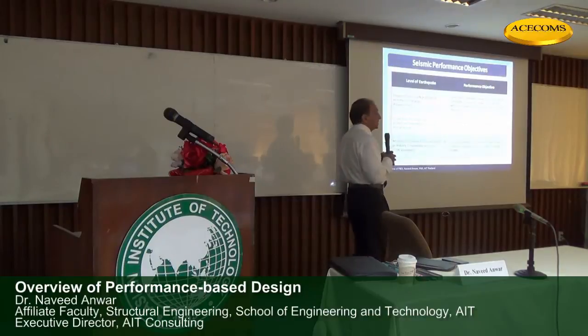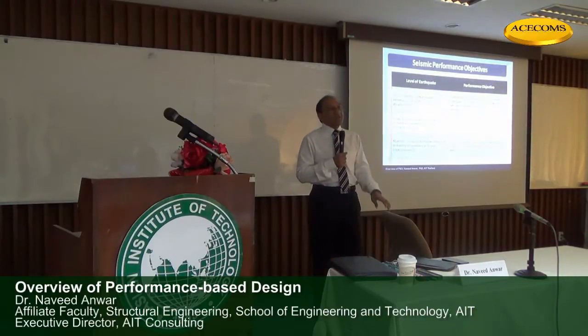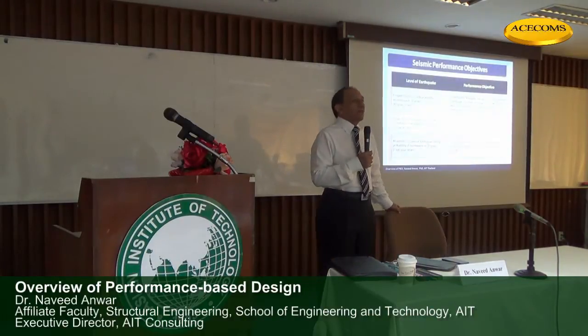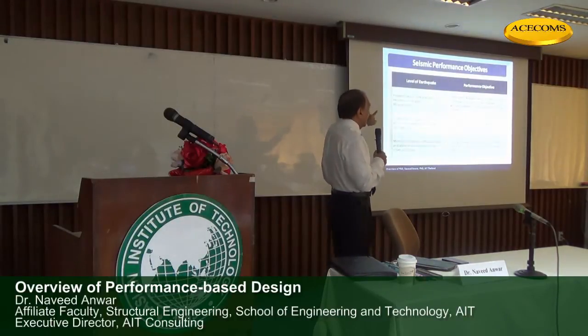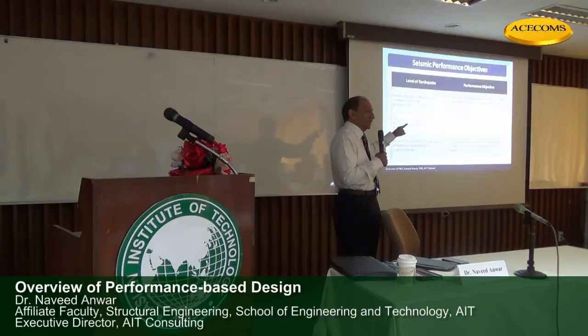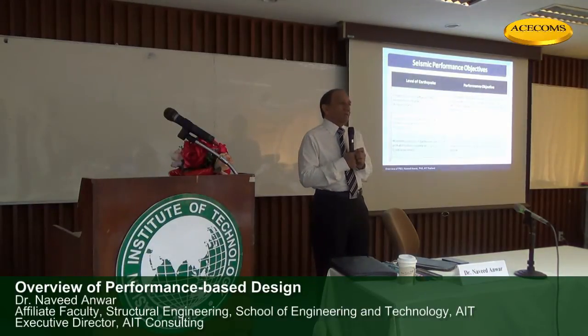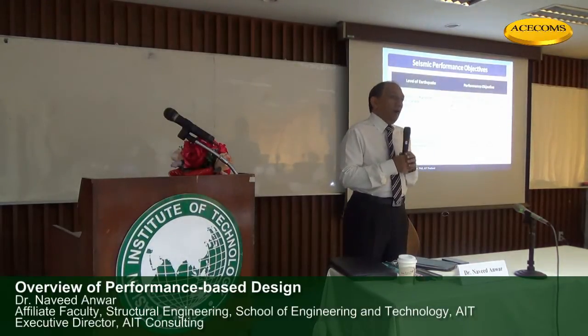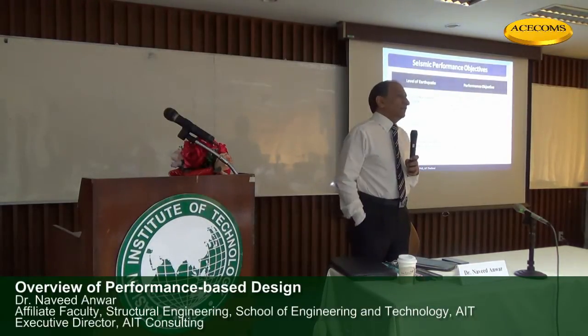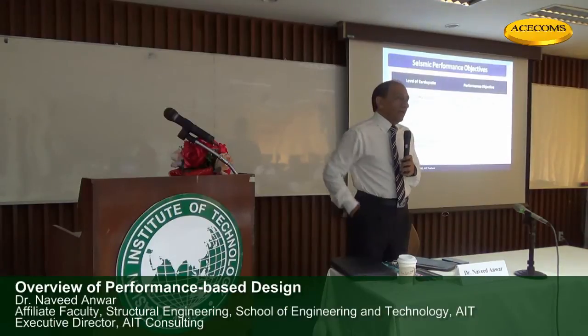Second level is the design basis earthquake, which is coming rarely, once in a lifetime maybe. This is the code level earthquake. And for that one we expect certain damage, but not too much. We expect the structure to become nonlinear. All of you who design have seen a factor in the code called the R factor, or response modification factor. We will talk more about that a lot.